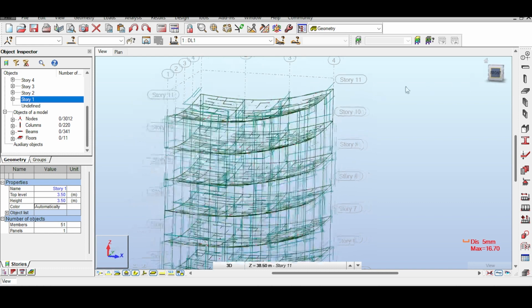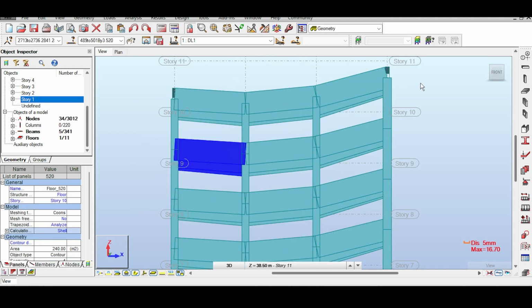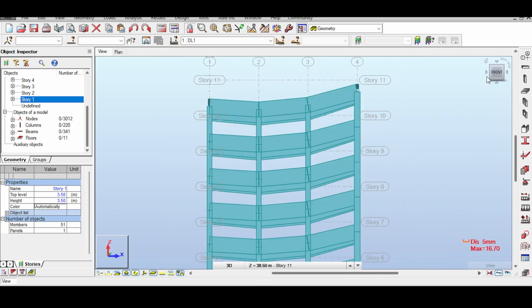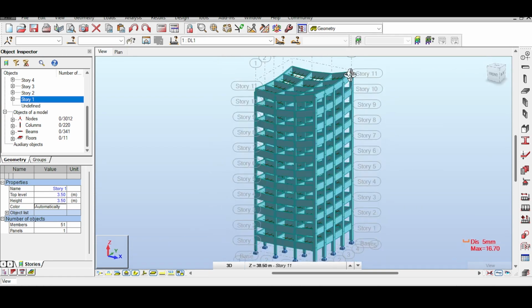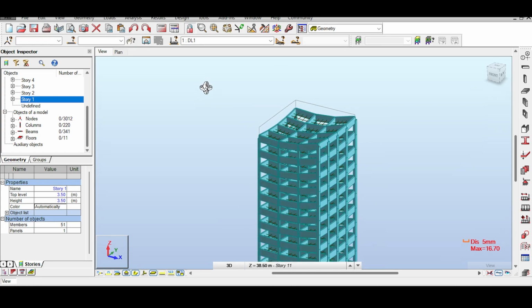This happens in some countries where the column is released from the beam and the lateral loads are carried by the shear walls. In that case, you have less to worry, but I will just try to solve this issue with our structure, where the columns and the beams are monolithically cast, or at least, where the columns and the beams are rigidly connected. So that's basically a good introduction to that topic.